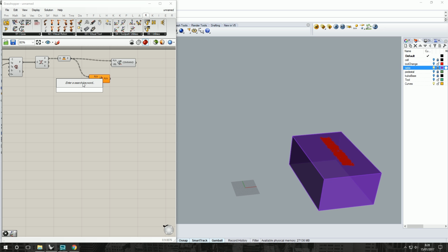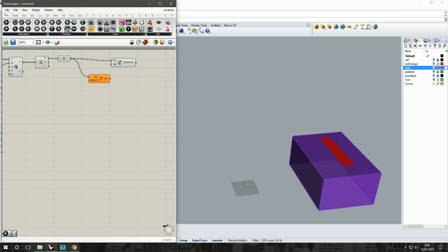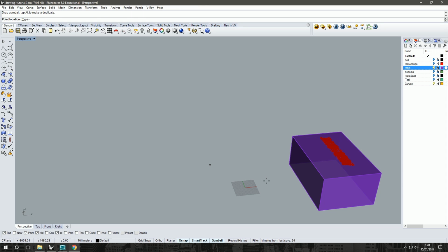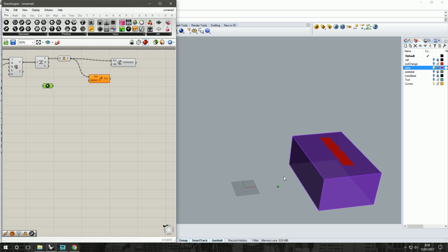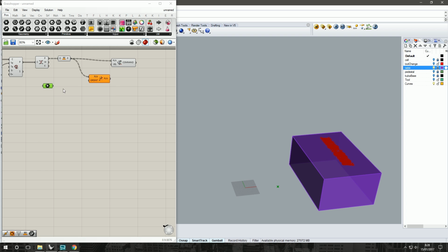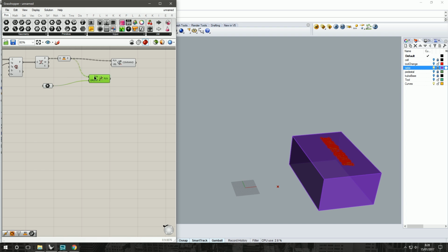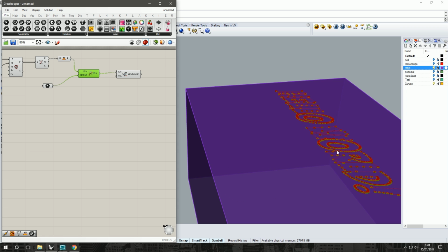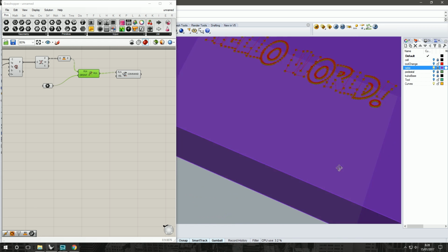We'll create a point, geometry point, set a single point. Let's say we want to orientate it to the front of the robot. And we'll put that in there. And instead of going straight from the planes into our linear movement commands, we can put it in there, and if we look in, we can see all of our planes have shifted slightly.